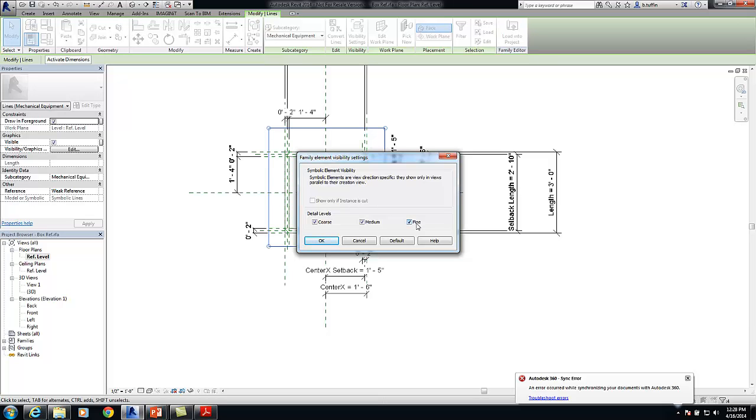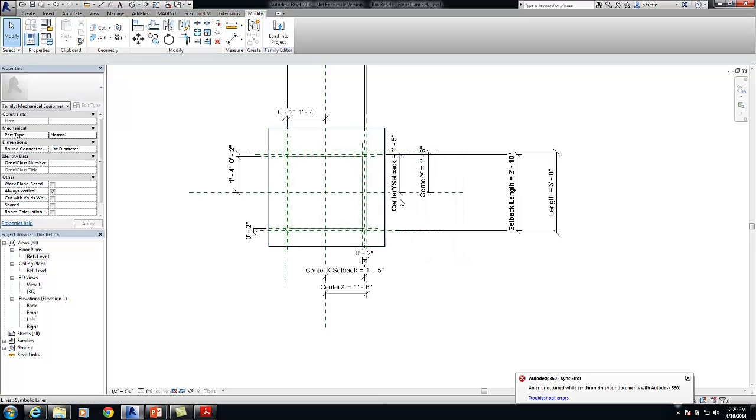I was working for a car manufacturer, providing BIM documentation for one of their plants. They had light fixtures that cost a few thousand dollars each. But inside of most manufacturing plants, you'll notice it's not just things that are happening on the floor. There's multiple levels of movements, conveyors, this and that. About 70% of their lights, once they were installed and the plant was up and functioning, they could not change. So once one burnt out, they'd just buy another one and hang it somewhere else. Doesn't make sense. So in a BIM environment, why not incorporate these clear zones, these spaces, along with it?